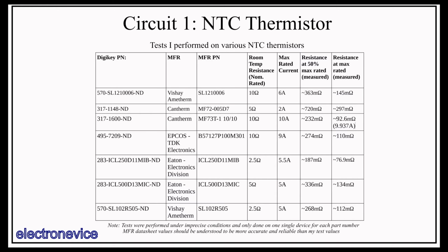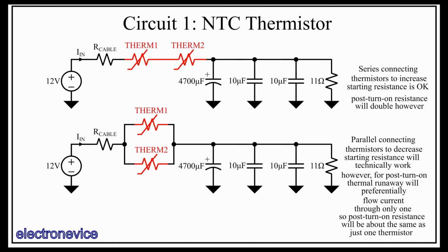One final note on NTC Thermistor circuits. If you need more starting resistance, you can put multiple thermistors in series and get increased starting resistance at the expense of increased post-turn-on resistance. However, putting thermistors in parallel is a much different situation.